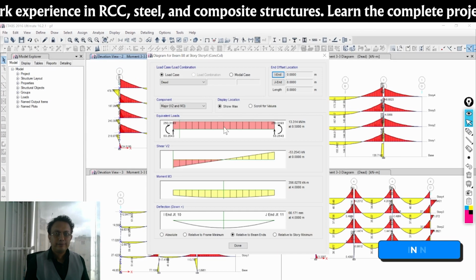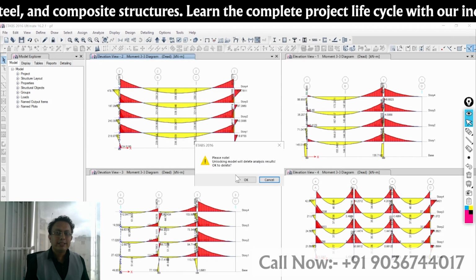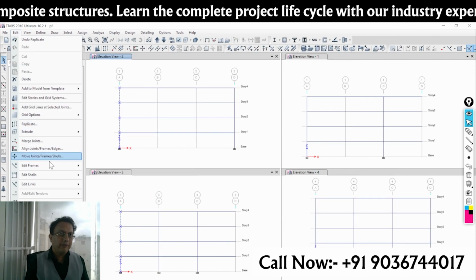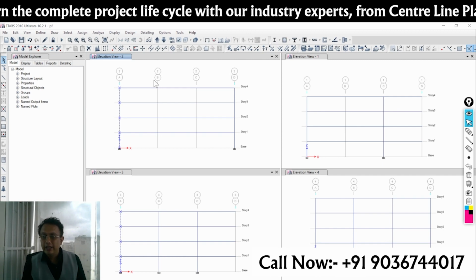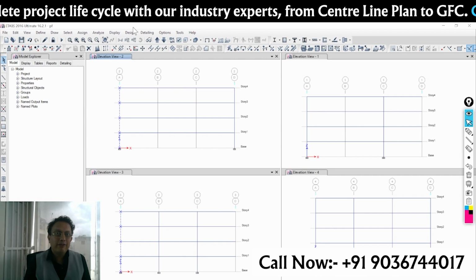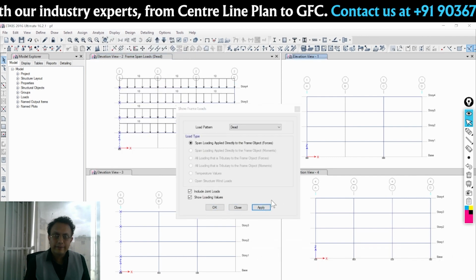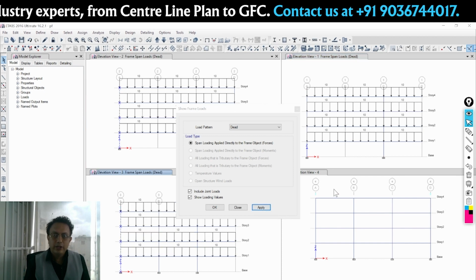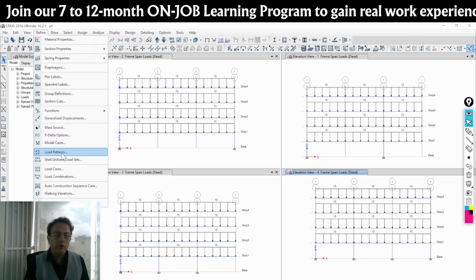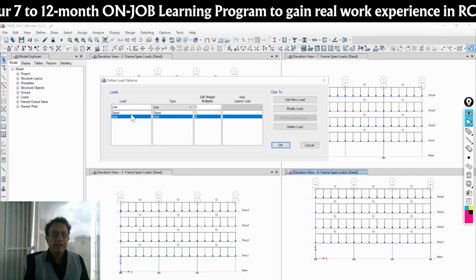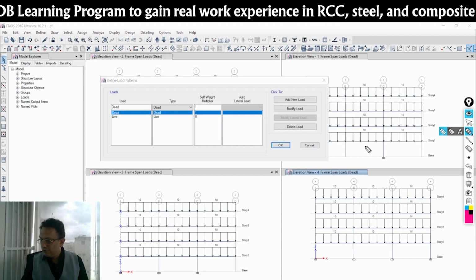Now, the moment I say that this is the value and all, but where are the loads? I have given certain loads, 10 kilonewton per meter. In that also you will see that there is self-weight. So if you want to calculate, please understand this very carefully. Everywhere I have given the values, which is like this. This is the load value that is given. But apart from this load value, there is one more value, what we call the self-weight multiplier, as 1.